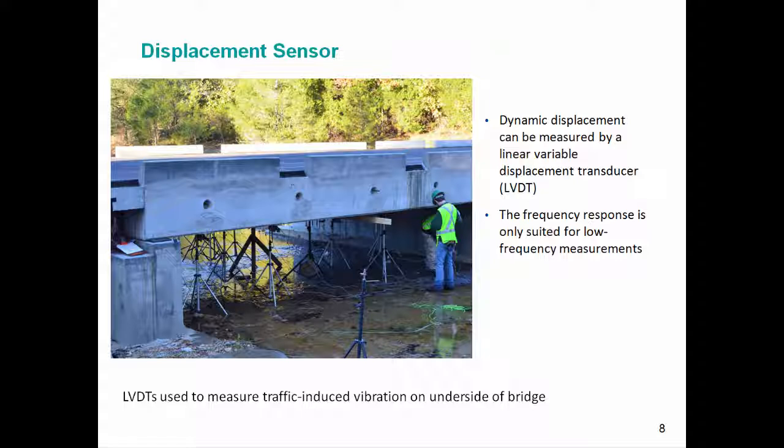Well, LVDTs certainly have their place, and they can be useful. Of course, displacement primarily happens at lower frequencies, so for the low frequency vibration that this bridge is going to undergo, the LVDT is a good way to measure that. But if we have like a small electronic box, avionics component with a circuit board, then that most likely would be subjected to higher frequency vibration with a corresponding higher frequency response, and the LVDT would just be impractical for that case. But they're great for example, for civil engineering structures.